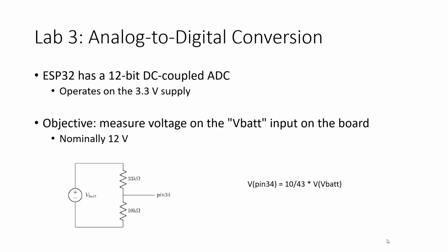The battery would be 12.6, but it doesn't go higher. I thought the battery could go up to, okay, 12.6. So you need a 4-cell to get up to 14. Okay, so we were assuming a 3-cell, right? So we're assuming a 3-cell lithium polymer, lithium ion battery. The fully charged voltage is 12.6, you said. But as the battery's capacity goes down, the voltage goes down. And so you can use the voltage as a clue as to what the state of charge is in the battery.